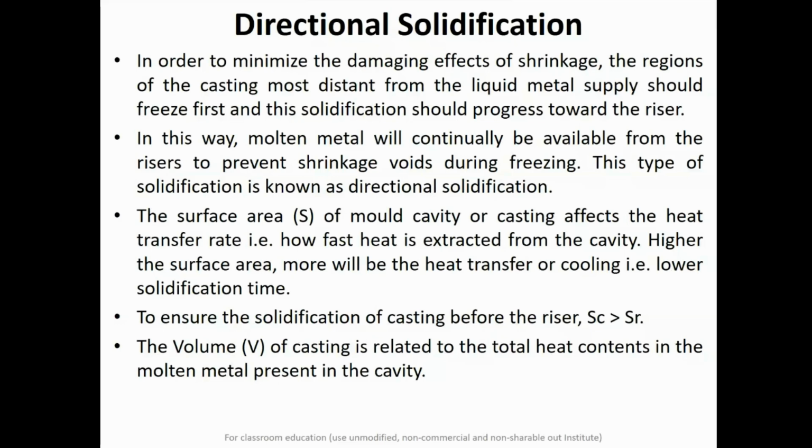Another important factor which comes into the picture here is the volume of the casting, and it is related to the total heat content in the molten metal present in the cavity. So the ratio of the surface area of the casting to the volume of the casting is equal to the cooling characteristic of the casting. And if this ratio of surface area to volume is more than the surface area of the riser to the volume of the riser, then your riser will solidify last as compared to the casting.